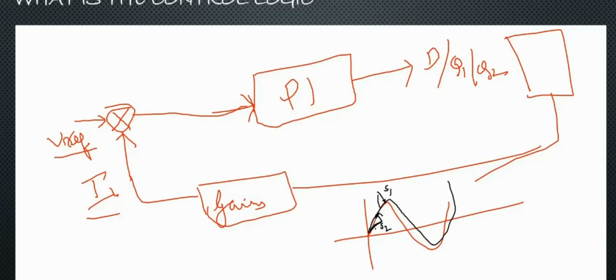But, yeah, this is a huge deviation which I've mentioned, but we have a very good PI controller and a very high frequency, so this happens at a very minuscule level. It's going to have a few milli or microampere deviations happening here, which means the current sensor should be of really high precision. It's going to happen something like this. Essentially, how much of this overshoot or undershoot happens depends upon the PI.